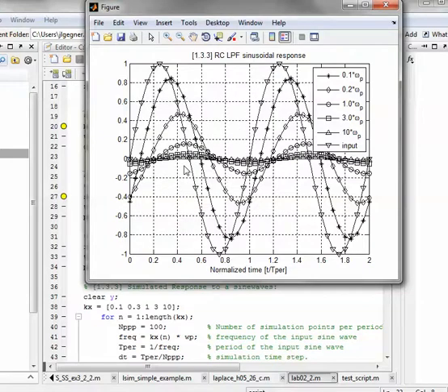So here's that time domain response to different sinusoidal frequencies. What I've done here, and what you're going to be asked to do, is that although the sinusoidal input is changing in time, the pole frequency for this RC filter is omega p, whatever that is for this particular design, I don't remember.